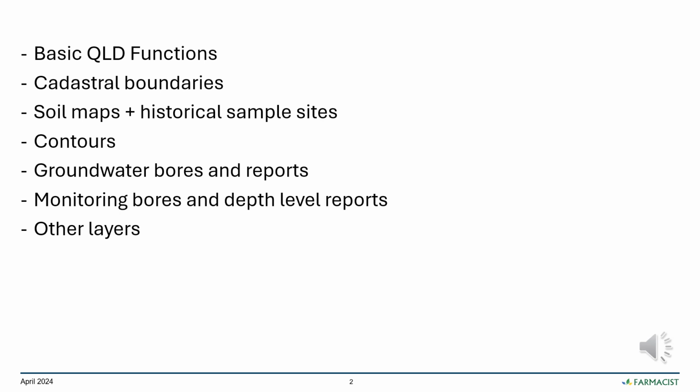Today we're going to be going through some basic Queensland Globe functions. So this includes how to use the program, finding cadastral boundaries, soil maps, historical sample sites, contours, groundwater bores and reports, along with monitoring bores and depth reports, as well as a few other different layers.